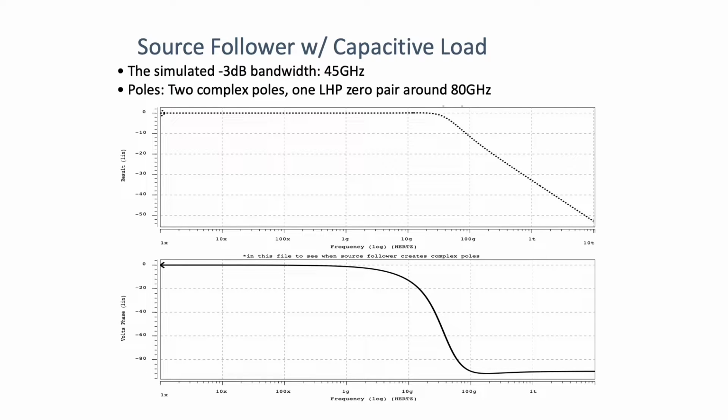So we said that it should be 2 poles and a zero. When you have 2 poles and a left half plane zero, your phase should transition only by 90 degrees. So it should drop, in this case, going from 0 to negative 90 degrees eventually. So the excursion of the phase is correct. The final slope of the amplitude plot is also correct: you get a negative 20 dB per decade slope, right? So that's correct.